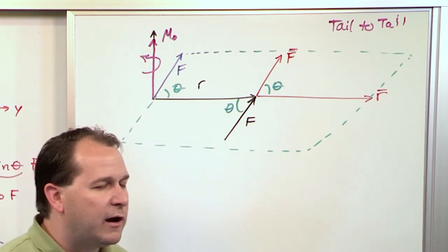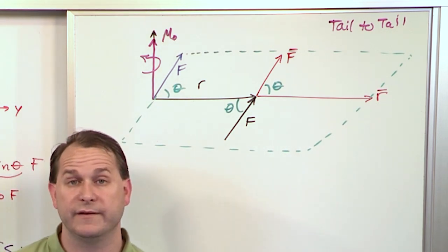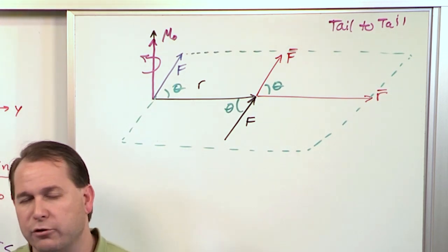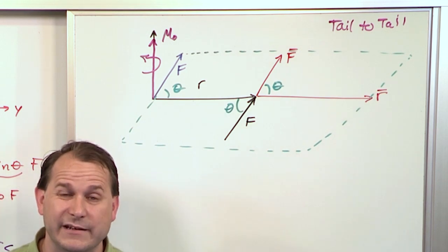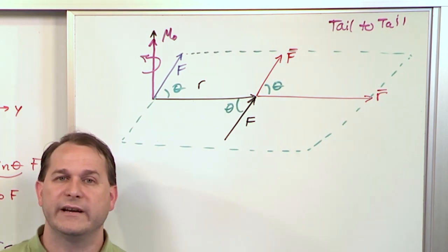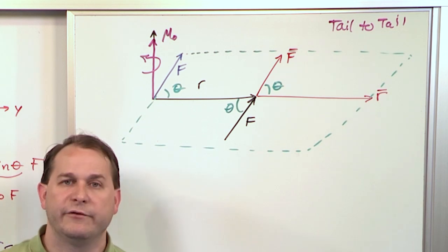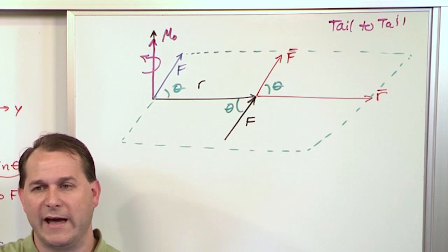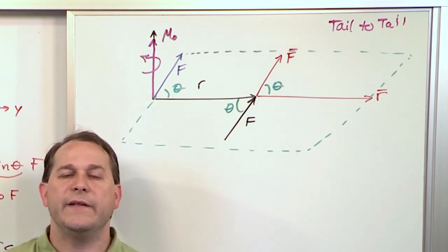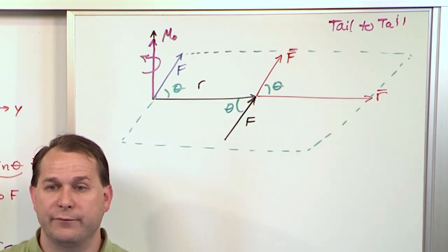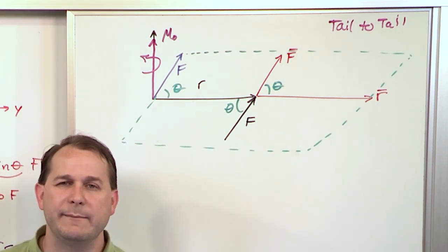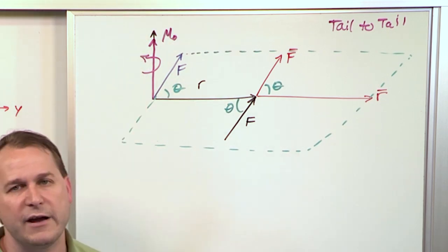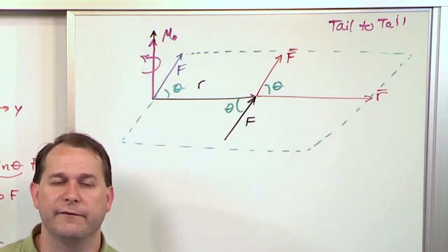Okay, now we already talked many times before about the concept that if we have a positive moment, meaning a counterclockwise rotation, we're going to consider that positive, and then if we have a negative moment, we're going to consider that clockwise rotation. That's really appropriate and very useful for two-dimensional problems when we have either left-hand or right-hand rotations. In three-dimensional problems, you can literally have rotations in any direction, so it's much easier because if you're going to add moments together, you just take the vectors that come about and add them up. The algebra takes care of the direction.